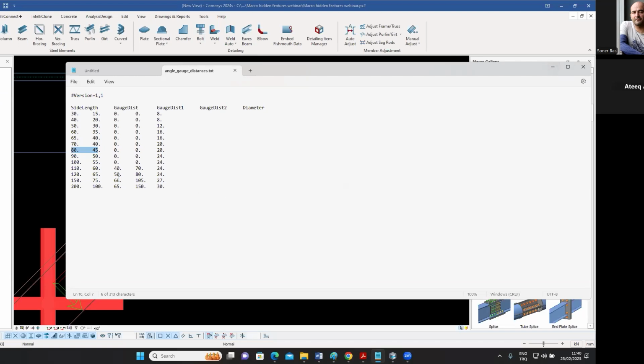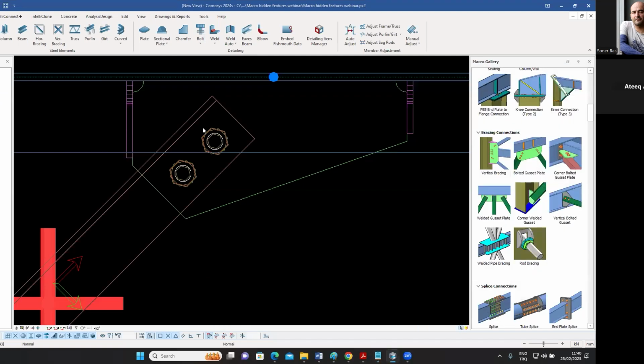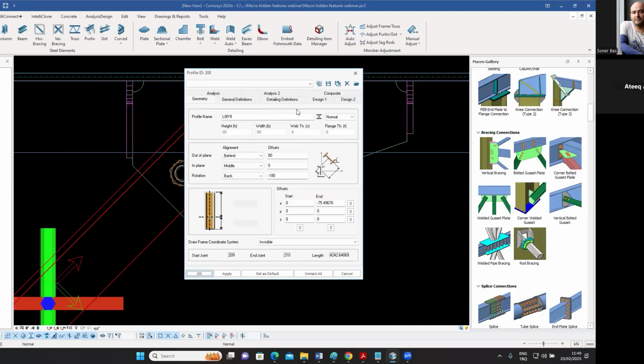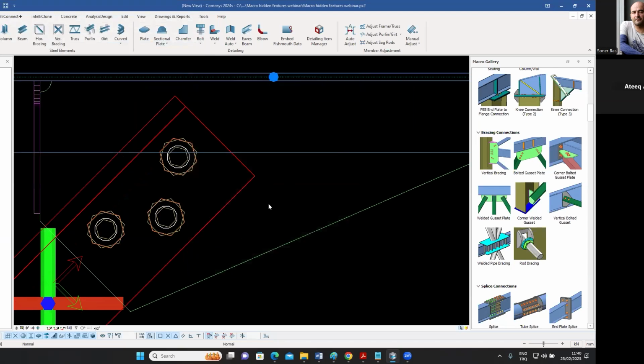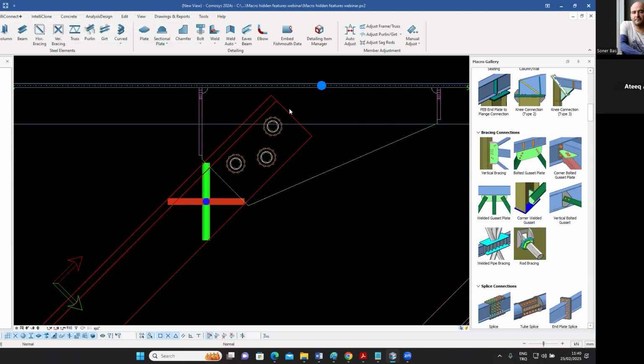So for example, if I were to use a higher, let's use this one, a 150 millimeter leg length. So I don't know what we have. Let's see. So if I use 150 by, or 150, do they have a 150 by? Okay, so let's this one. And if I do that, you see that it is immediately put two lines of bolts staggered.